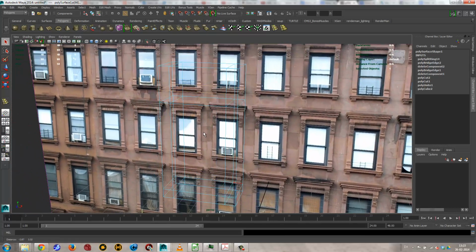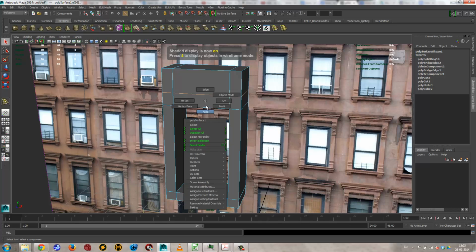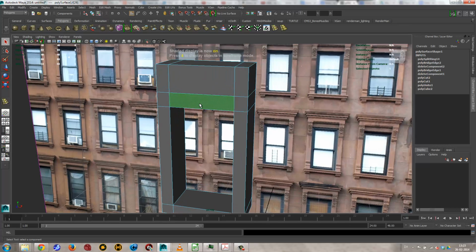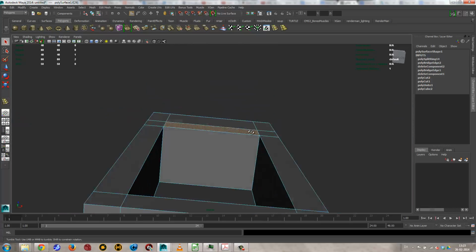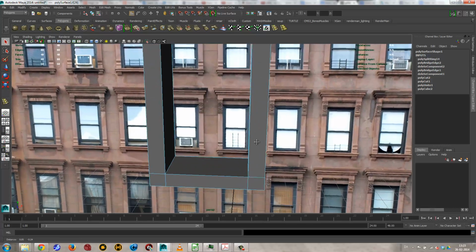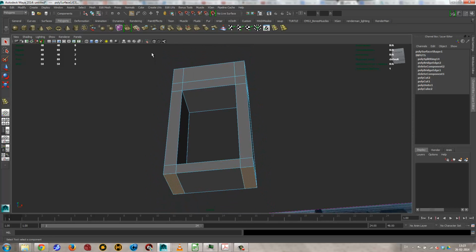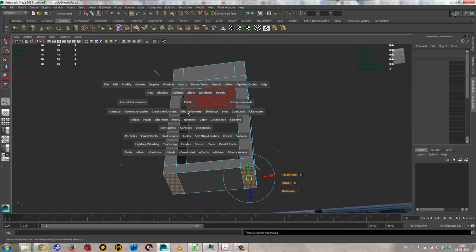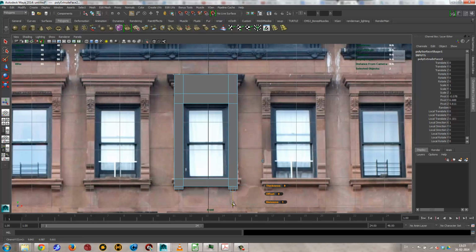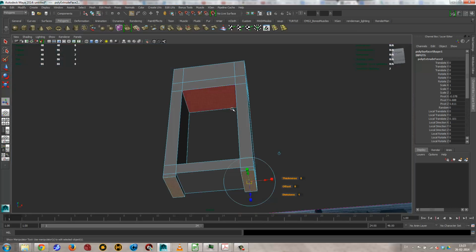And then for the bottom here, see, now I'm sort of flying around this model, so what I'll do is select the face and press F, so now that is my center, and I'll rotate around that. I'll go to the bottom here and use extrude while in the front view, and just make this little thing going down to the bottom here, then back to perspective.